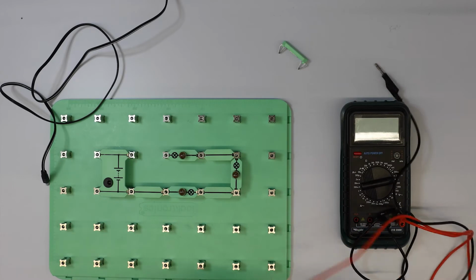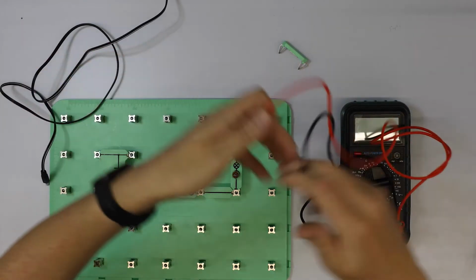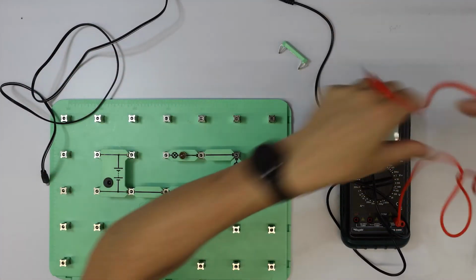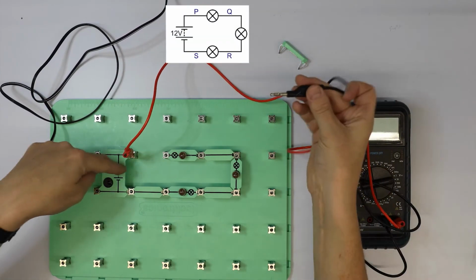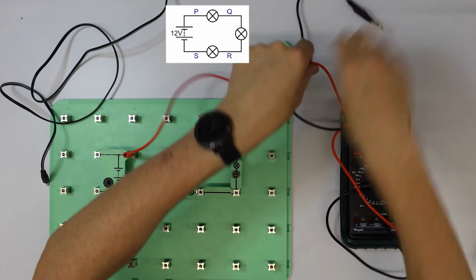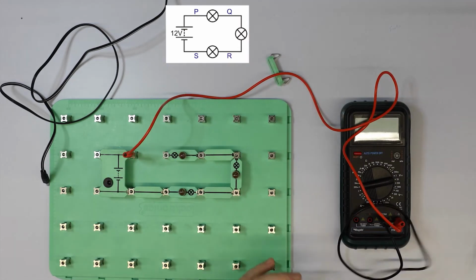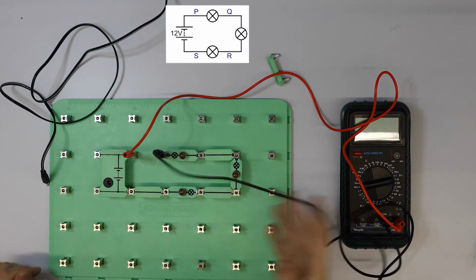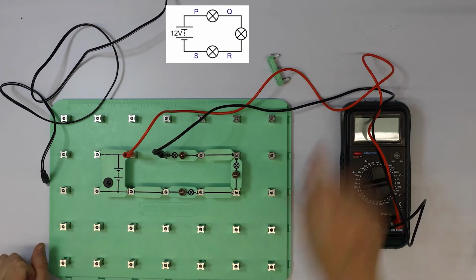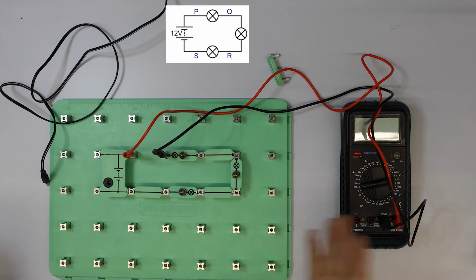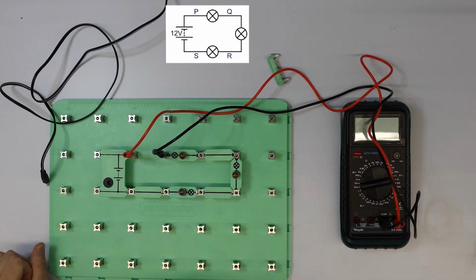Remove this circuit here. I'm going to connect, once again, the red lead to the positive side of the circuit, next to the long part of the symbol there, and the black lead to the negative part of the circuit. So it flows from positive to negative. Basically, if I connected it the other way around, it wouldn't make any difference. It's just the result on my multimeter will be negative, and that tells me that the current's flowing the opposite way to how I'd set it up. So it just gives you a negative value.